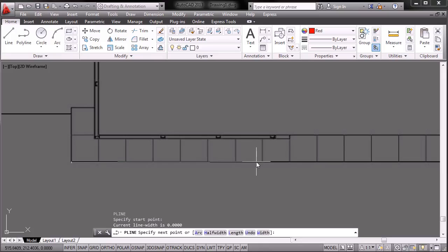But for that purpose, we can use our Auto tool over here and make it help us draw a straight line. So to turn on the Auto tool, we go down here to our guide tools and turn on the Auto. As you see now, our line is constrained to be totally horizontal or totally vertical. And this will help us to draw the contour of our project very quickly. So now we have our polyline tool on.